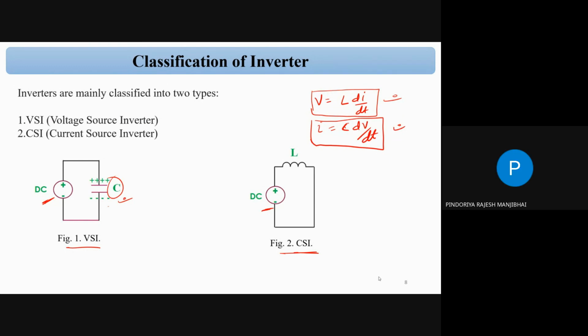Suppose we connect any inductive load, capacitive load, or RL load here, and then we can find the Thevenin equivalent circuit, and then we can find the impedance. Correct. Because the Thevenin equivalent circuit is nothing but a simple circuit. So this is VTH, and this is your RTH, and this is your load.